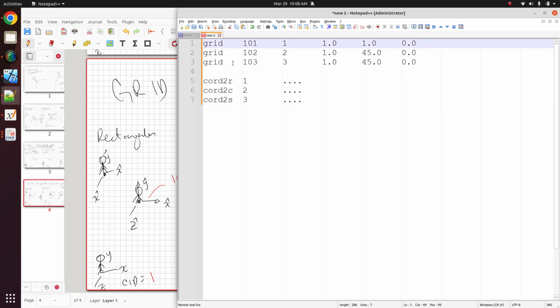If you go to this field, which is field 1, 2, 3, 4, 5, 6, and 7. In field 7, this is where you specify the displacement coordinate system ID. So here for the first point, we're going to say use coordinate system 1, use coordinate system 2, and then use coordinate system 3. But remember, we're not defining one displacement coordinate system.